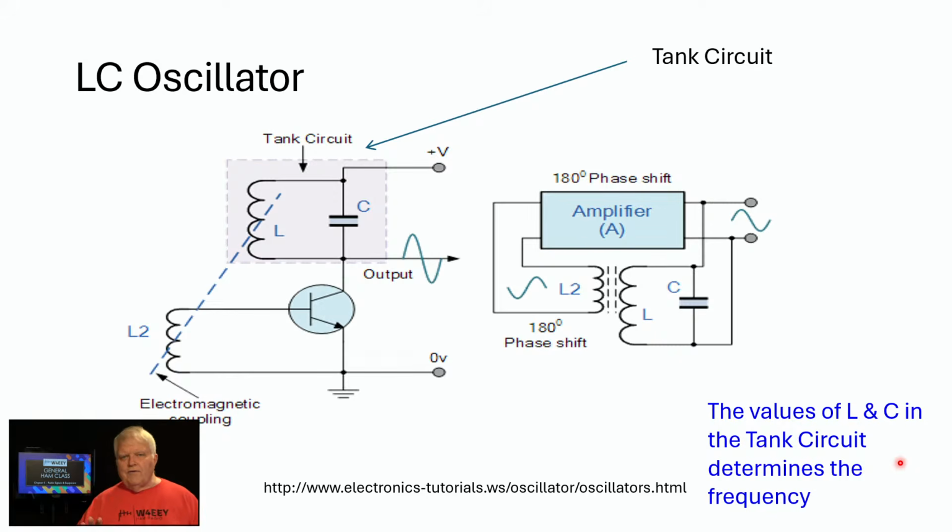So those were LC oscillators. You'll still see them sold at ham fests as external VFOs. They had their issues. They were tube type, so they had to warm up. Usually they were very drifty until they got to a stable operating temperature. Even then, they had a tendency to drift in frequency up or down.